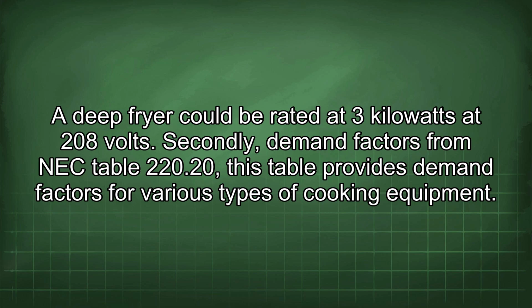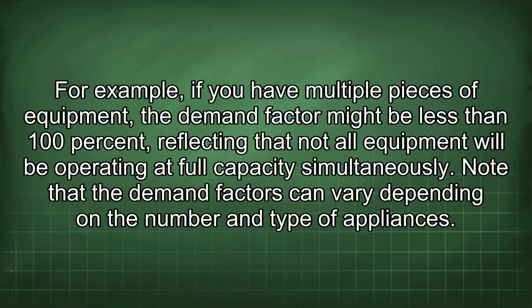Secondly, demand factors from NEC Table 220.20. This table provides demand factors for various types of cooking equipment. For example, if you have multiple pieces of equipment, the demand factor might be less than 100%, reflecting that not all equipment will be operating at full capacity simultaneously.